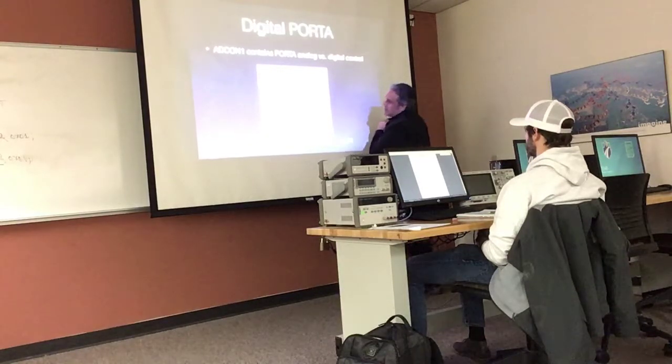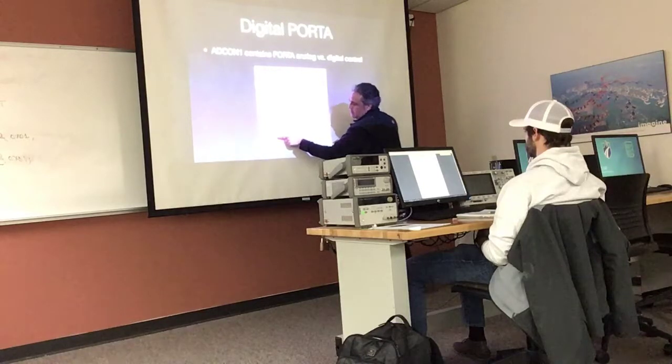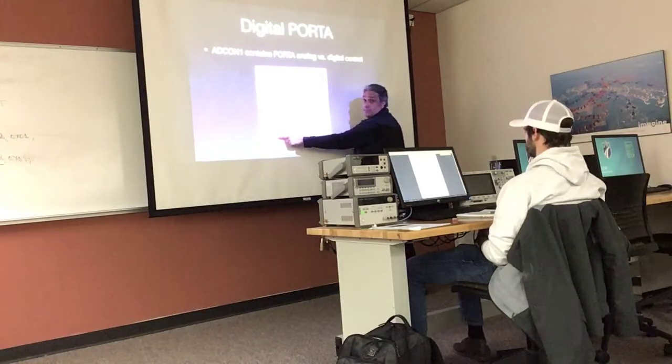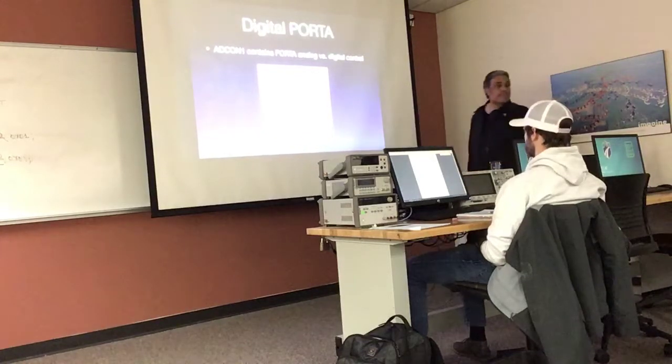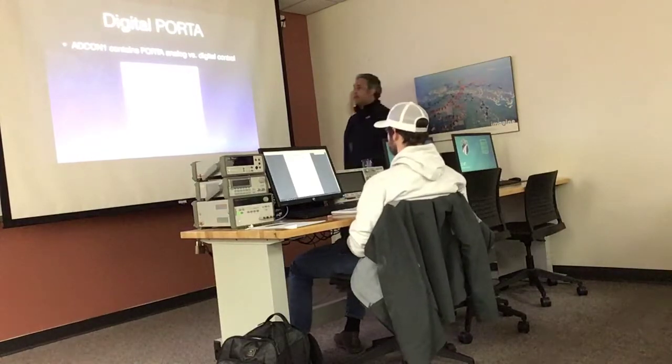If I want to make AN4 digital, right here, 4 is digital, but the rest are analog, you have to put there hexadecimal B. See that? You just have to read the table.